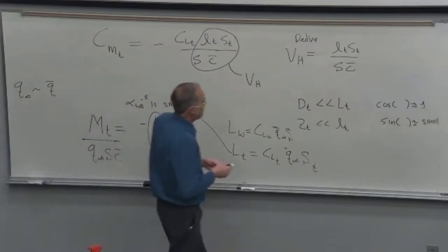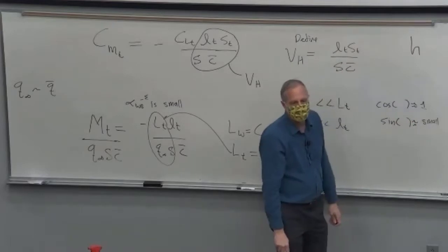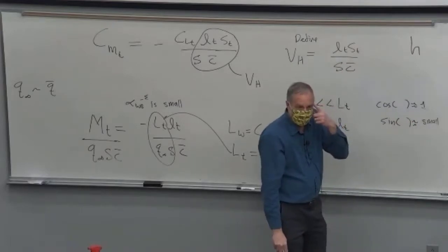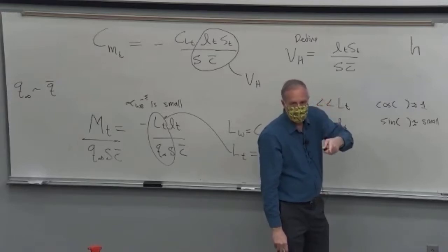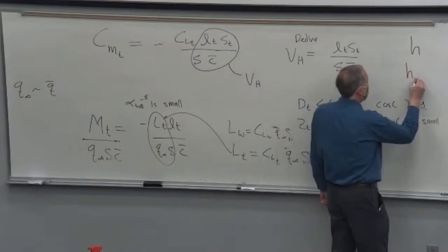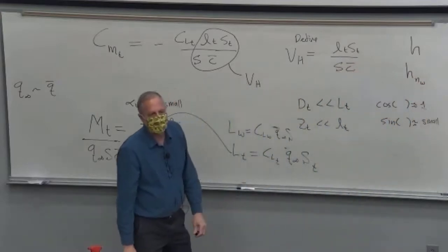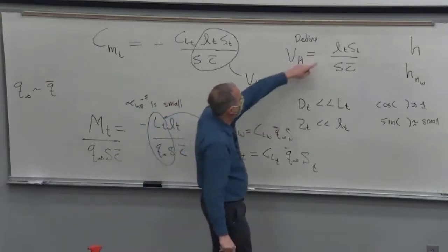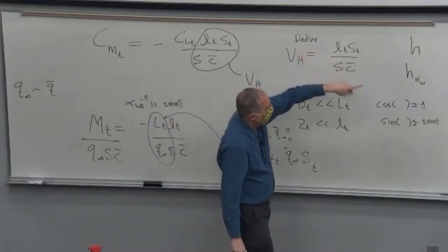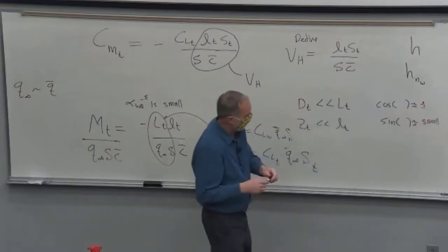Like, I will expect you to know what H is. What is H? You'd think, where is H? Okay, H was at the picture of the wing, and it's the distance to what? Center of gravity, in fractions of C bar, right? What's H in? That was the distance to the aerodynamic center of the wing. What's LT? Distance, center of gravity to the tail. It's just stuff you have to know.